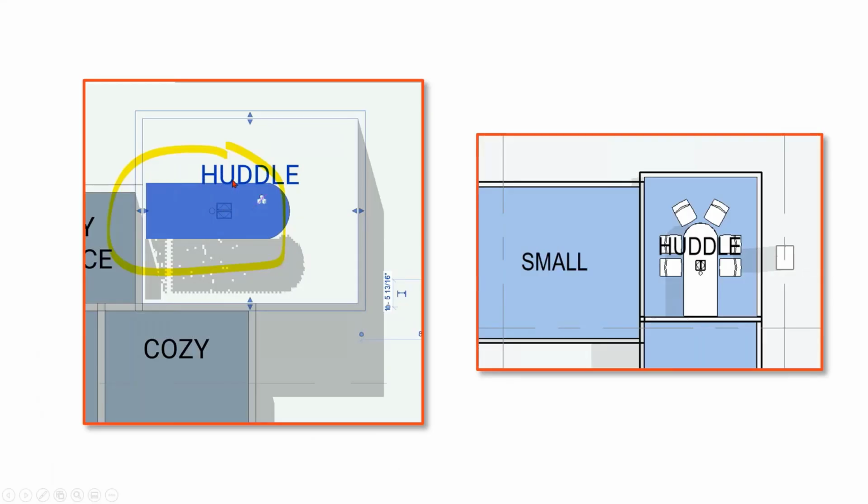One thing that we found with those boxes is that there's some visibility issues that may pop up. You can see this is one table and chair block, and there's no chairs showing up. So if you adjust the cut height or the height of some of the boxes, or adjust visibility settings, you can get to both. I've also told teams to just run the room tool, put it in, and use color fill schemes to do that.